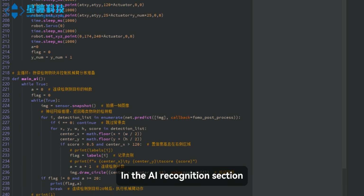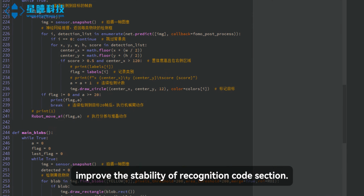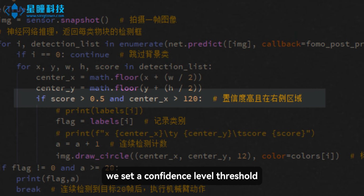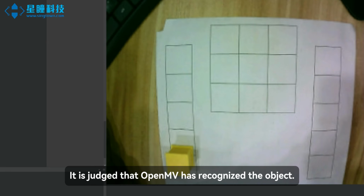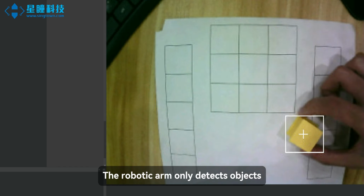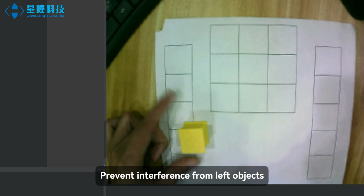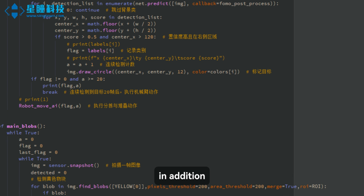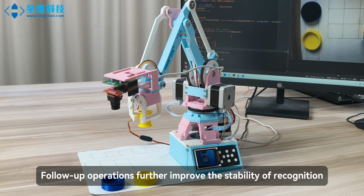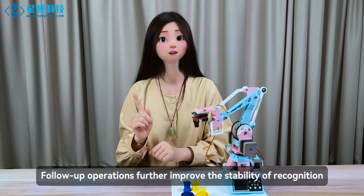In the AI recognition section, we made a special design to improve the stability of recognition. In the code section, given the identification result, we set a confidence level threshold. When the identified confidence level is greater than 0.5, it is judged that OpenMV has recognized the object, and we also set a detection range. The robotic arm only detects objects on the right side of the screen, to prevent interference from objects on the left. In addition, the robotic arm recognizes the object 20 times in a row before the follow-up operations, which further improves the stability of recognition.